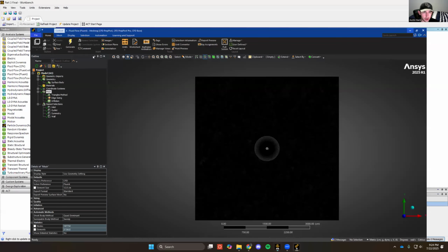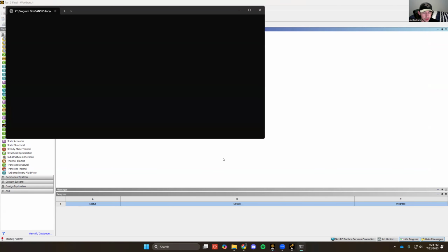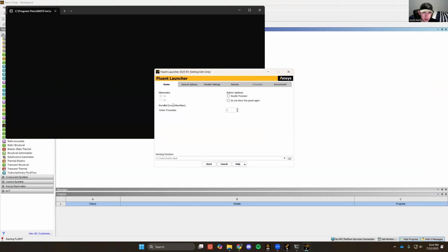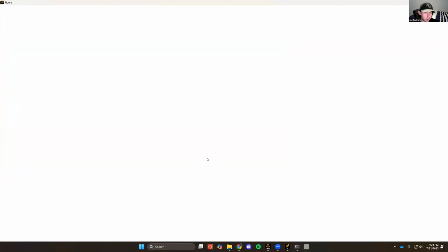And then we're going to go back here. We're going to update the mesh. Definitely make sure you update the mesh. For here, you want to click double precision. Depending on the number of CPU cores your CPU has, I have 6, so I'm going to put 6. If you put 1, it could take a long time. I would suggest putting the maximum of your PC.